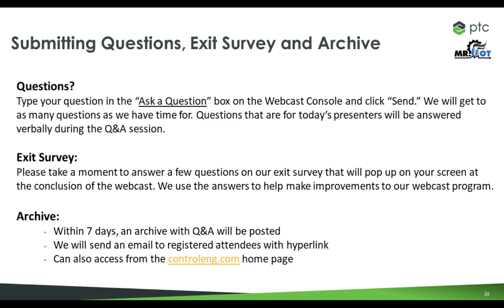Either of you like to address that? Yeah, a lot of machines aren't even online yet. And once you start bringing them online, if, say, it's a Rockwell PLC, it'll start spitting out a lot of data. It's very busy. It's even more chatty than your typical Ethernet traffic. So if the budget is there, I'm always for having a separate industrial network, hardware-wise. And nowadays, there's also 10 gigabit plus network switches and logical ways to separate the industrial from business networks and assign quality of service levels.